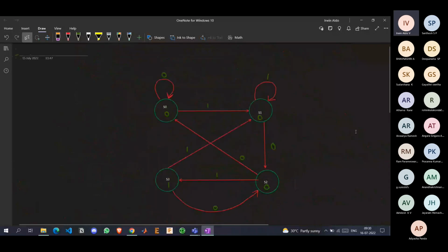This is our state diagram. We first break our logic into different states or levels, and define the paths where each input value gets us to. In this case, we have 4 states, so we need 2 flip-flops.